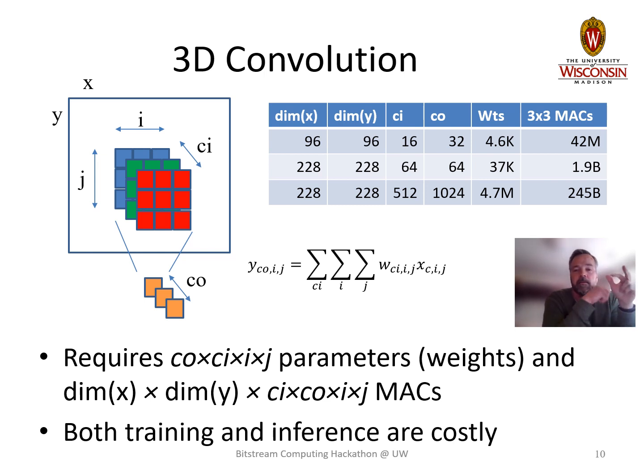So again, the camera will typically give you 3 channels, but in these intermediate layers in the network, you'll want at least 16, all the way up to 1024 channels. And so you have some channels on the input side, you have some channels on the output side, and the total number of each of those is what ultimately determines the total number of weights and the total number of multiply accumulates that you need to execute in order to evaluate that layer. And then to do the whole network, of course, you have to add up all those for all the layers.